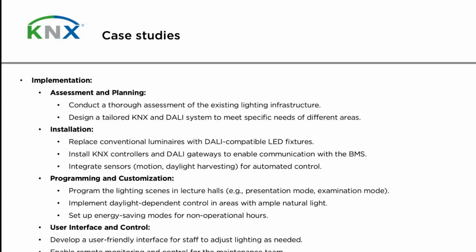Let me tell you something. If you plan to build a new building or you are going to change the lighting fixture and you are planning to implement DALI, ask your supplier to supply the lighting fixtures with the ECG DALI instead of 0 to 10, instead of whatever regular dimming ECG.